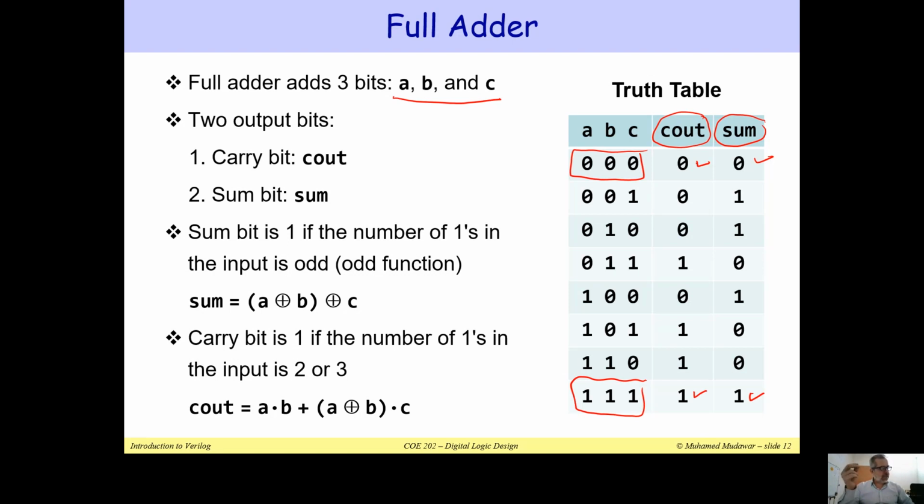Okay, so basically the carry has a weight of 2 in binary. In decimal, the carry will be 10, but in binary, the carry is only 2. Right, so you can see that this is the truth table of the full adder. For example, let us take another entry.